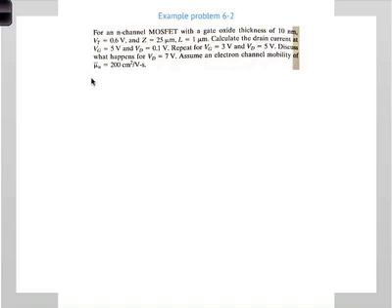The condition for saturation is related to the drain voltage: the drain voltage is greater than or equal to VG minus VT. Remember, that's the situation where right at the drain, you get pinch off, so the depletion eats into the inversion.